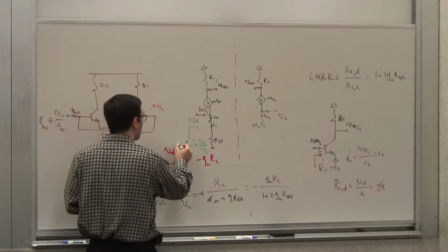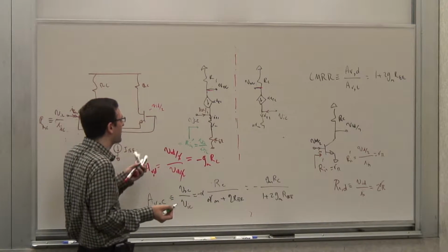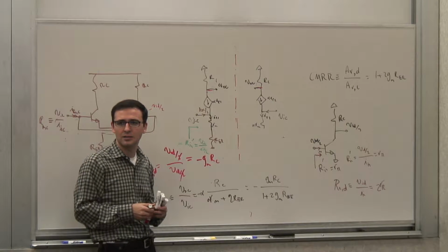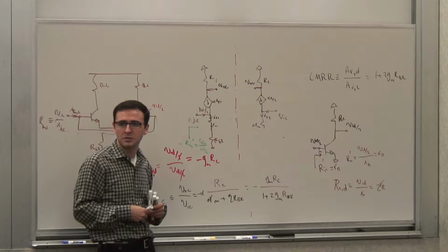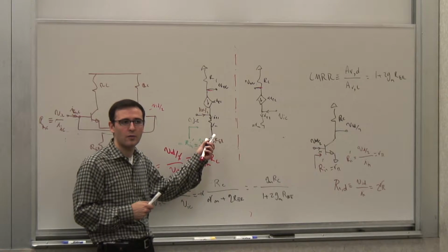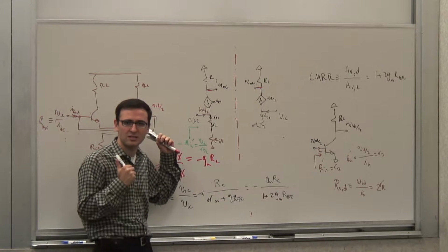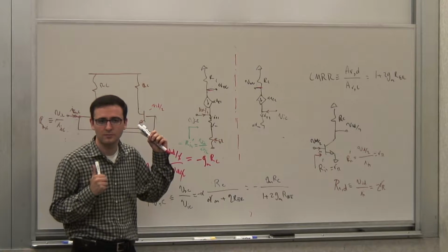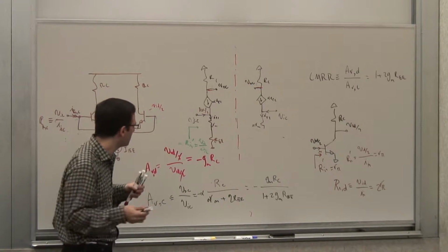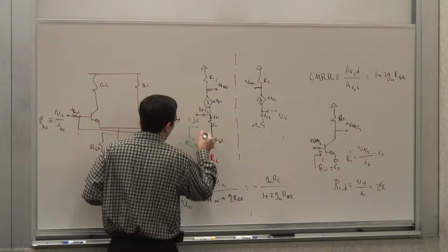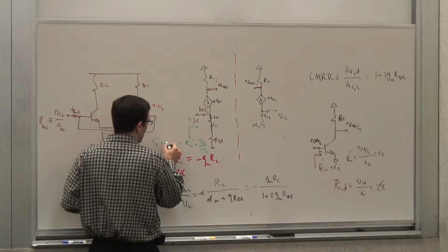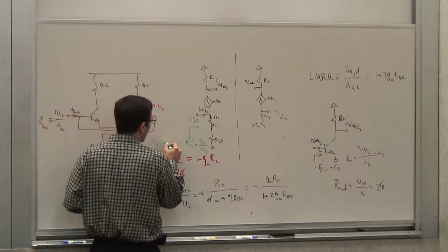And what is that input impedance? Well, that's nothing but the input impedance of a common emitter with emitter degeneration. How do I calculate that? Remember the reflection rule. I have stuff in the emitter, I want to move them to the base. I'm looking at it from the base side. What happens to them? They get multiplied by what? 1 plus beta. Yeah, beta. So this gives me an R pi, and that gives me 2 beta RE.